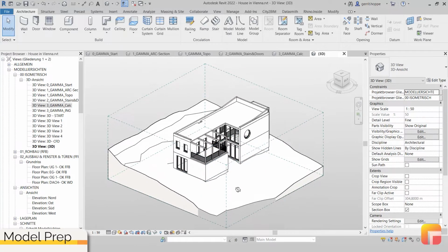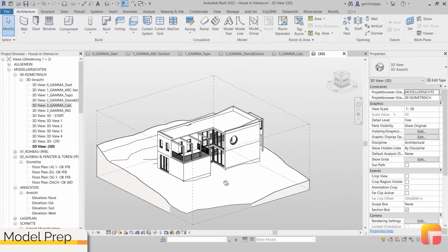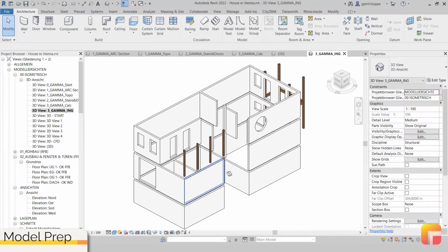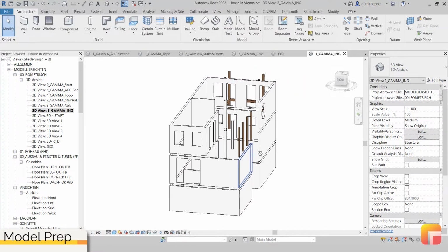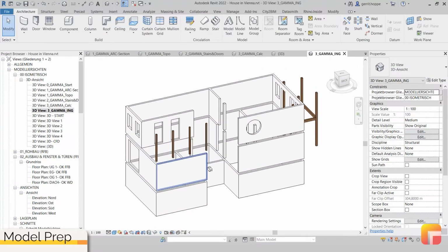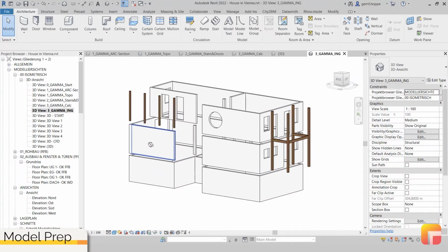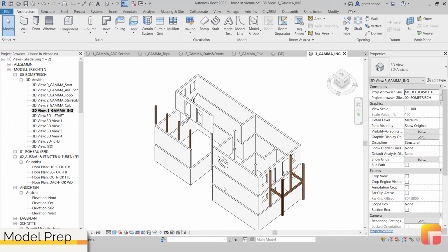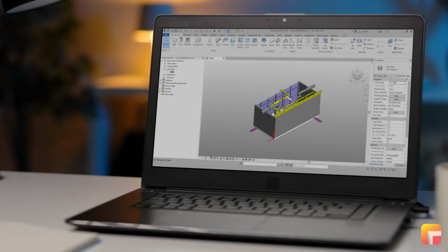Even though Gamma AR only requires at least one wall, space, or column to be exported, as a general rule of thumb, it makes sense to have at least some, if not all, load-bearing architectural elements visible. This makes it a lot easier to position yourself later on, as well as being able to ascertain the location of the planned 3D model information in respect to the environment being built on site.